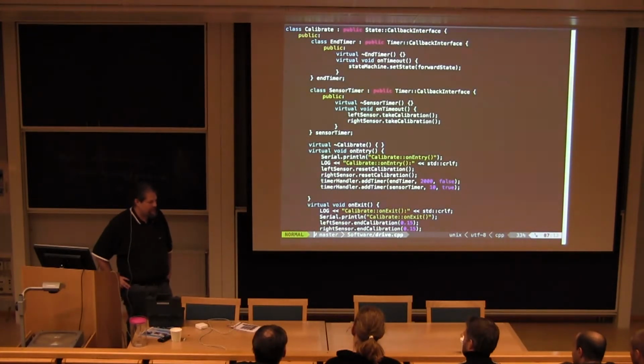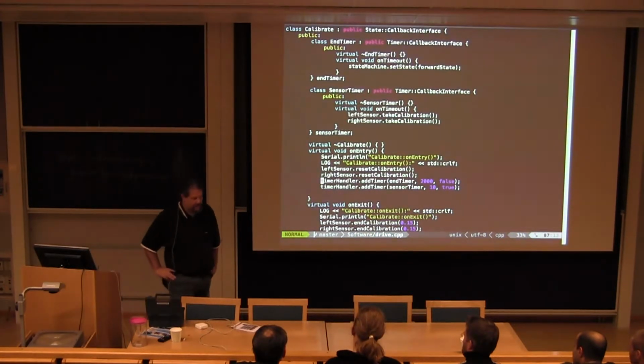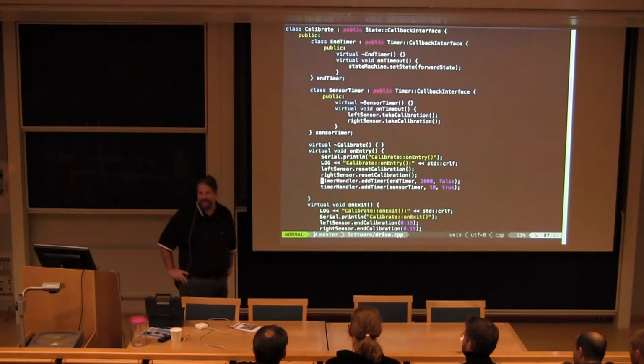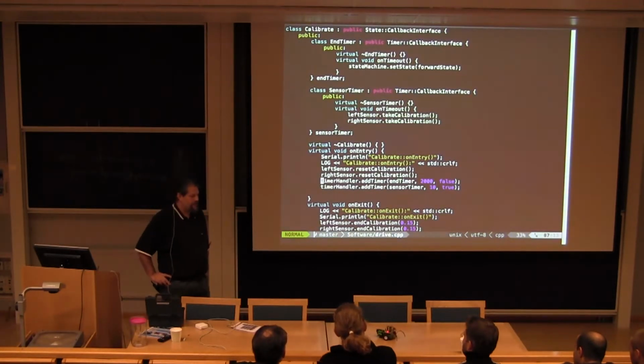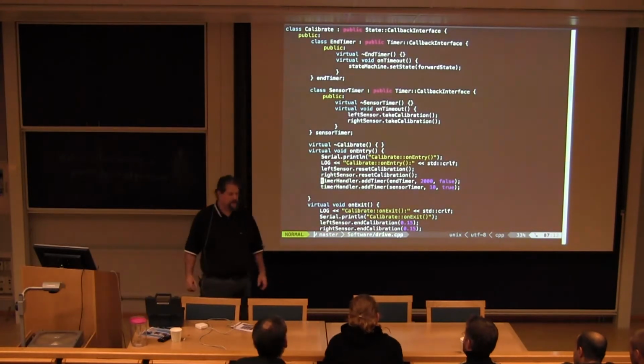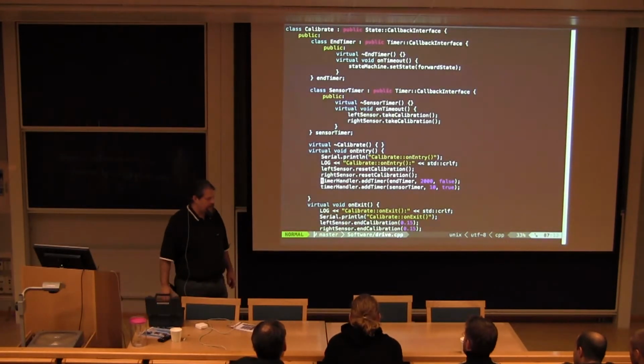There are a few things more I have to do with this robot. You can see here when it runs long distance that it is not running straight. That is because putting the same voltage on the engines doesn't make it run straight. So I have sensors, encoders on the wheels, that I'm not reading now. They have to be hooked up and read to see what speed I actually get from the engines.